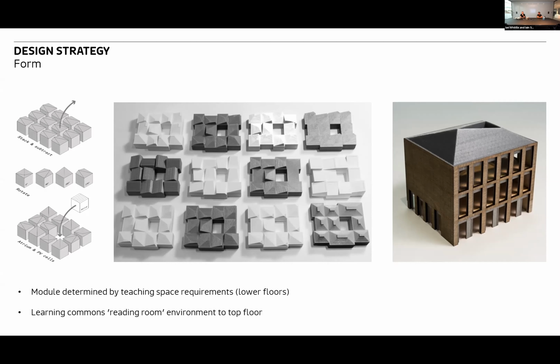And essentially what we established was a brick box which had a window elevation and a more blank gable elevation, capped then with a traditional standing seam zinc roof, that's then sliced off to give a triangular roof light, which provides light into the deeper top floor learning spaces. So that was really the key move in developing the form and the organisational strategy for the building.